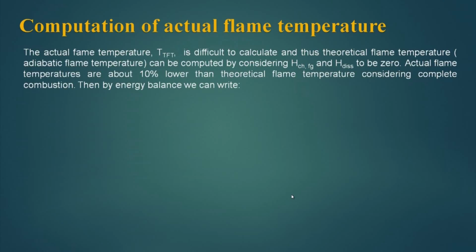Now, the actual flame temperature is difficult to calculate, and thus the theoretical flame temperature, which is called the adiabatic flame temperature, can be computed by considering H_CHFG and H dissociation to be 0. Actual flame temperatures are about 10% lower than the theoretical flame temperature considering complete combustion.